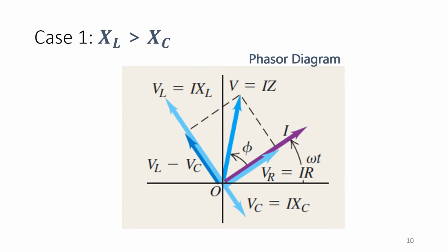If you remember, total voltage will always be out of phase from the current, but resistor voltage is always in phase with I. This only means that it's the inductor and the capacitor that contribute to the phase difference of V and I. So if you notice here, VC is pointing at quadrant 4, VL is pointing at quadrant 3, and then VR is in line with I. So really, this misalignment of V is because of these VL and VC.